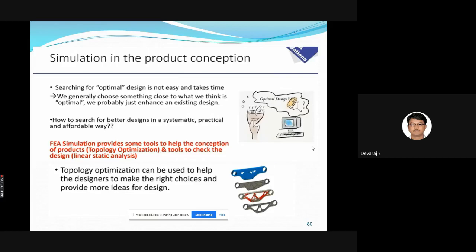Right, students? So this is the best example. If you go for an engine part, you should check fatigue, you should check creep. In industry, you should do all the analysis for the engine. But when you come to the fuel tank, there's no need for creep. Fatigue for the fuel tank may be required, but creep is not, because the temperature only varies from 35 to 45 degrees, only 10 degrees.